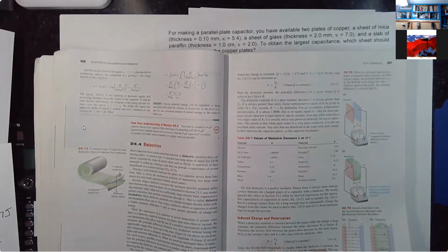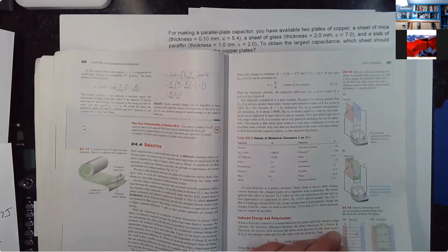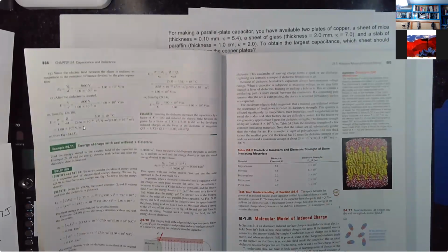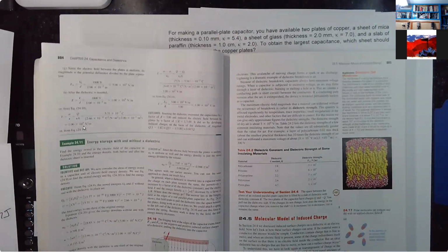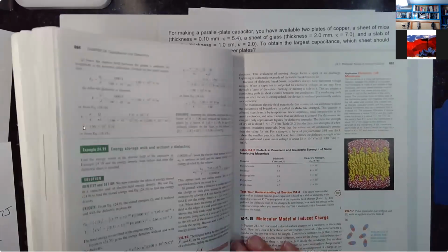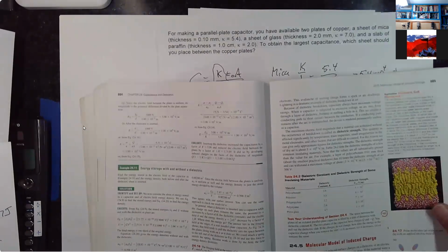And so you realize that you can make Teflon super thin, but then you have a capacitor where you can only charge it up to a particular potential difference, because otherwise you break the dielectric down. But that's something that also would have to be taken into account with the design of this thing.